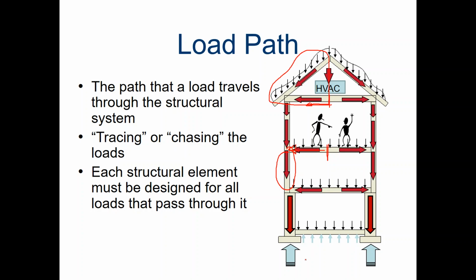And so that is how load paths work, and we'll talk about chasing that load through the building. Essentially what you want to do is take all the loads from the building and work your way down, and in the end those loads should be all transferred into the foundation and from there into the ground.